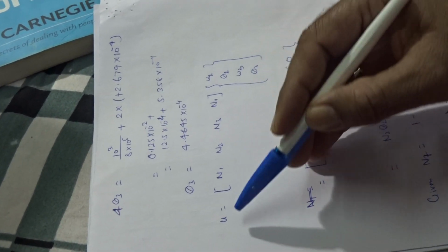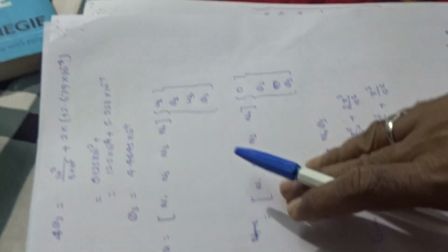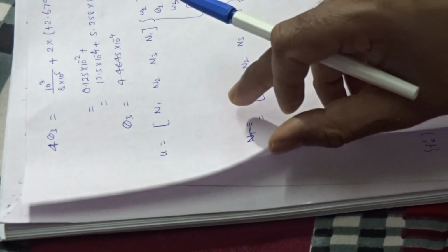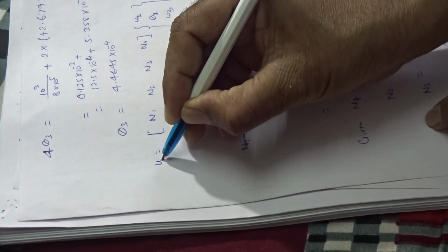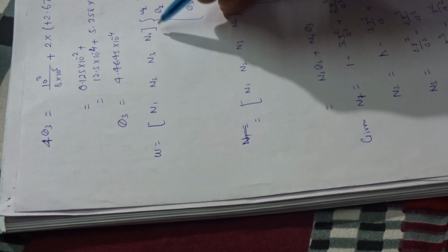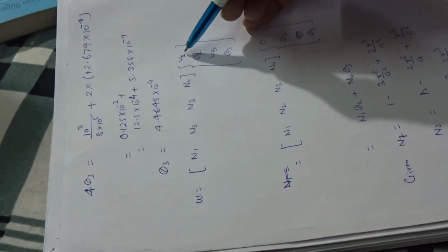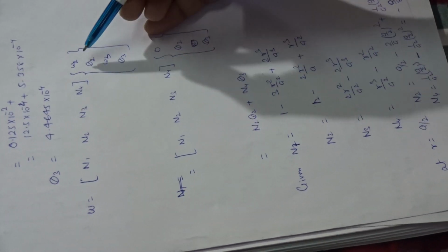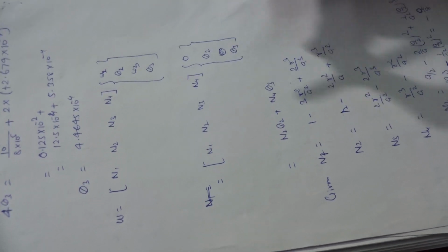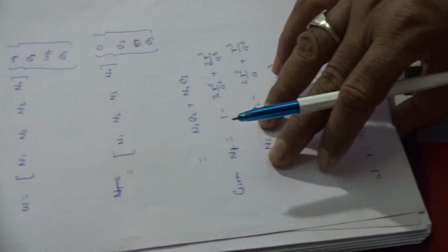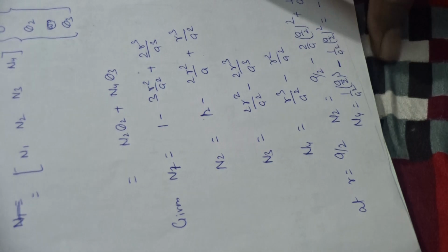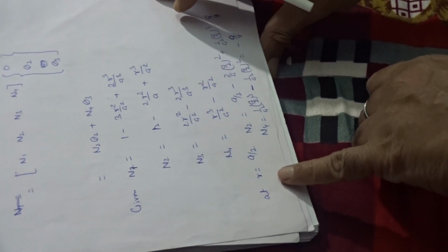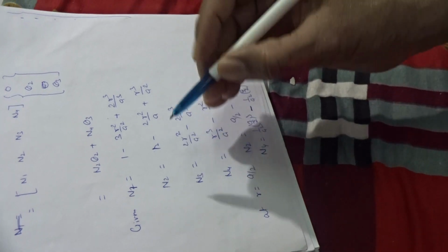And we have to find the deflection at the middle of the UDL load. This is denoted by W. So W is equal to N1 N2 N3 N4 for the second element, times W2 theta 2 W3 theta 3. W2 is 0 and W3 is 0, so W is equal to N2 theta 2 plus N4 theta 3. We can write N1 N2 N3 N4 from the previous equations already derived at the start in the theory portion.